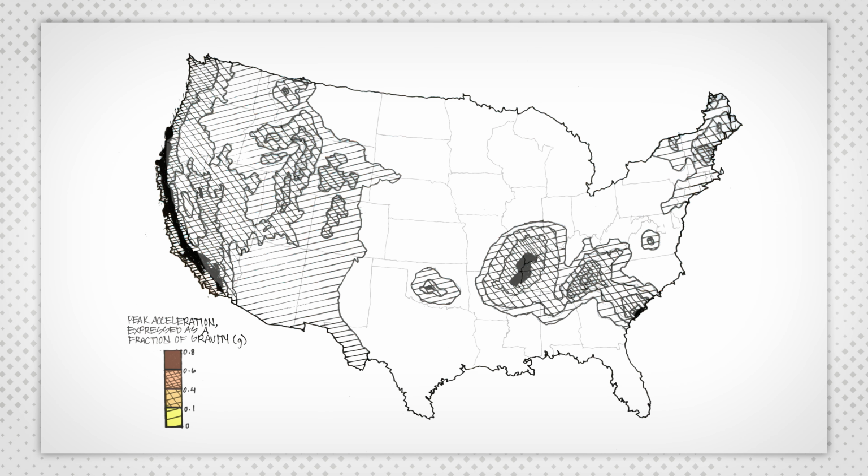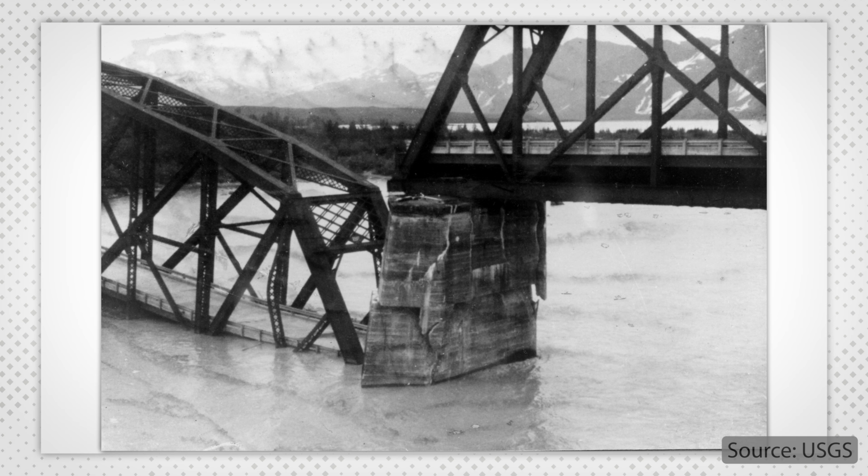The magnitude of potential seismic activity varies significantly across the United States. The West Coast, portions of the Intermountain region, the Mississippi River near Memphis, and the South Carolina coast have the greatest seismic risk. Maps like this one provide seismic data such as the peak ground, short period, and 1-second accelerations. Engineers use these to predict the seismic effects on structures.